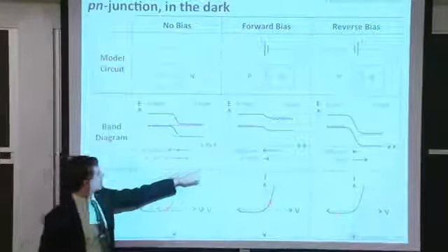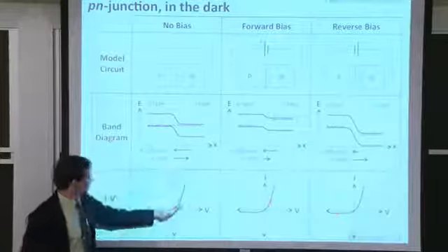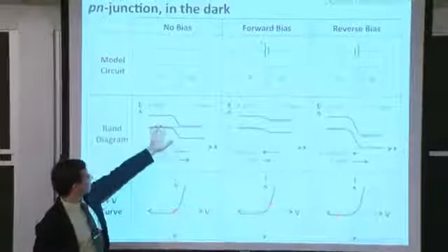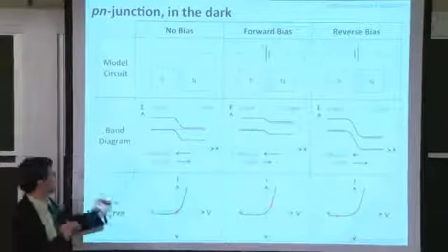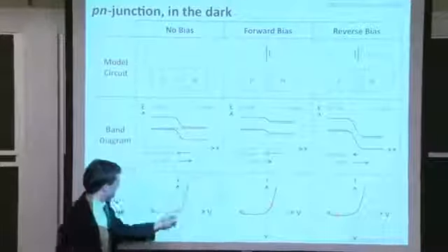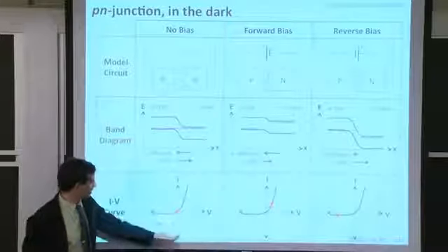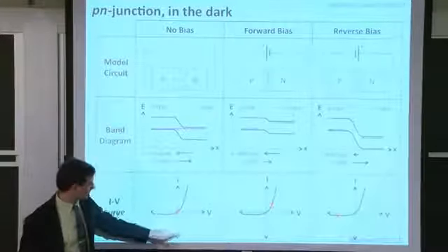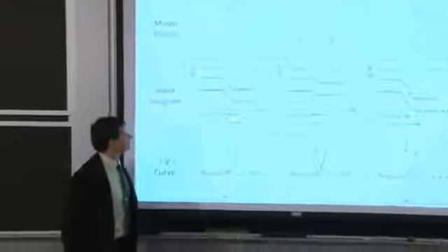And we would add an illumination current, an arrow pointing to the right here, which would mean that we would have current flowing through our device, but there's still no difference in the chemical potential on either side. There's still no difference in Fermi energy in the P-type and the N-type, which means our voltage is equal to 0, which means we're intersecting the y-axis right here. And our little x should be marked right down here. So it's really just a superposition.